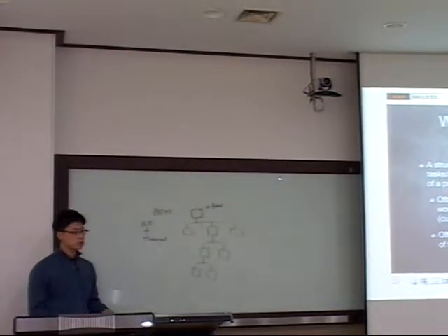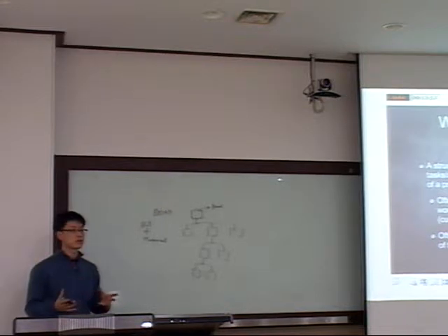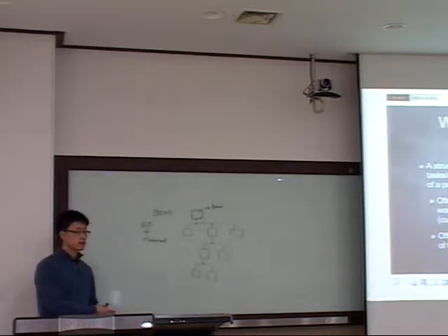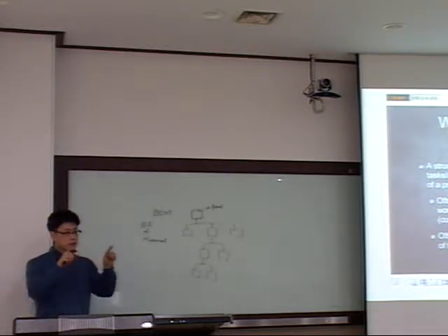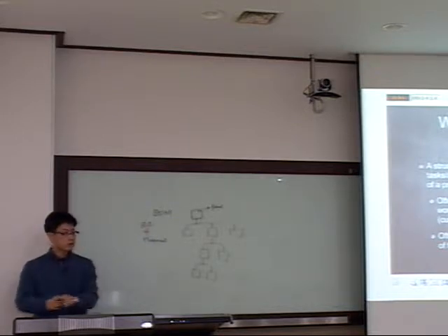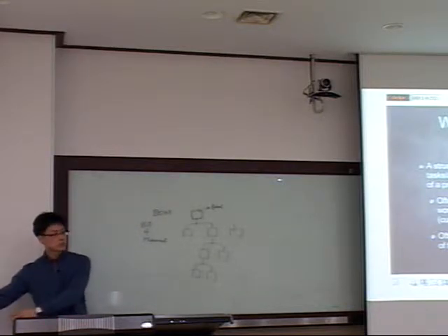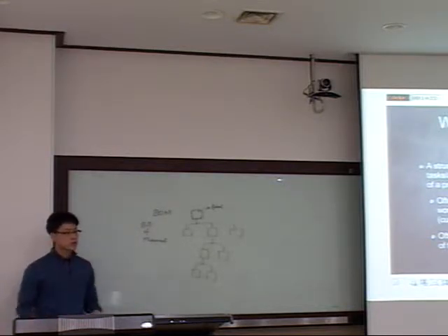For example, in order to make some assembly, you have to cut some part from the flat plate first and have to align it and weld something together, finally make that sub-assembly. So build block 101 actually includes many other subtasks: cutting, material handling, aligning, joining, something like that, which can also make this breakdown structure.